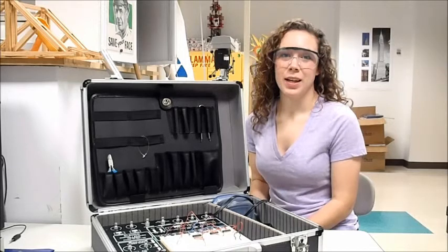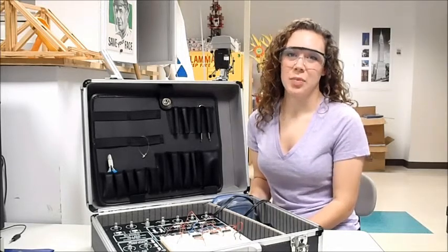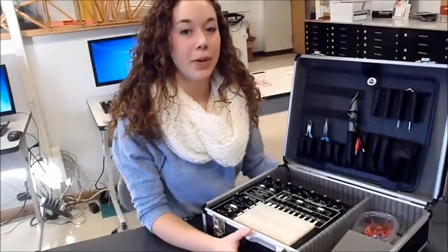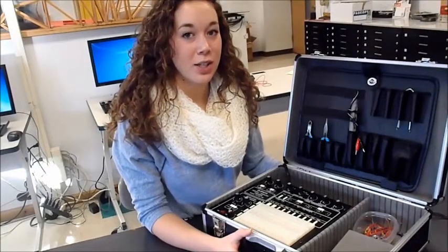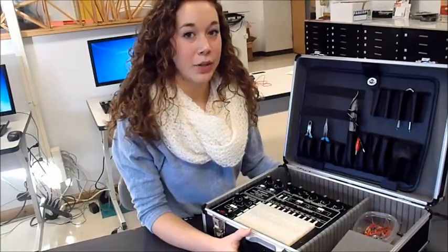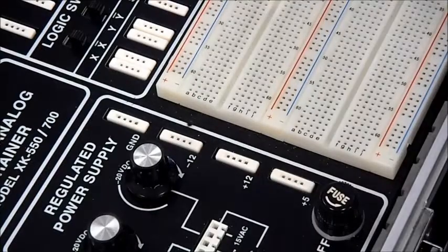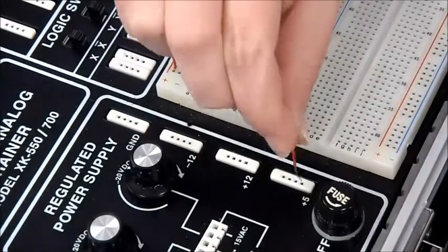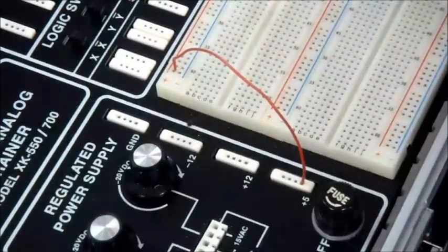I'm Professor Steppenbeck, and I'm the breadboarding and circuitry technician at Project Lead the Way Incorporated, and I'm here to teach you about breadboarding. This is a typical breadboard that we will use. The first thing you need to do when breadboarding is hook up the power and the ground. The first thing you do is plug the positive bus into the power supply, and then you plug the negative